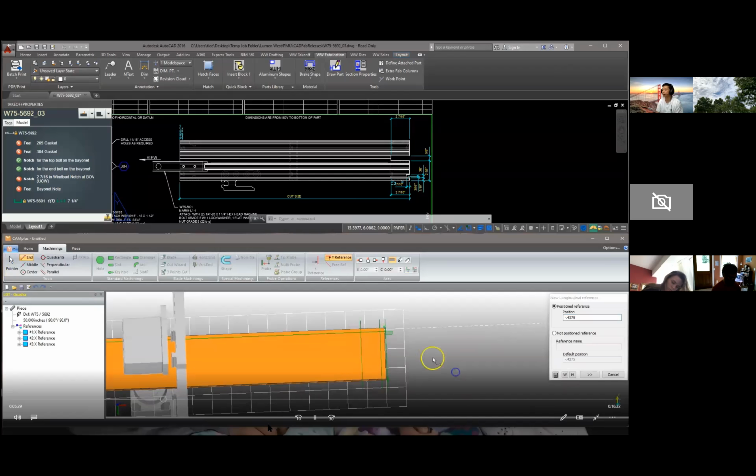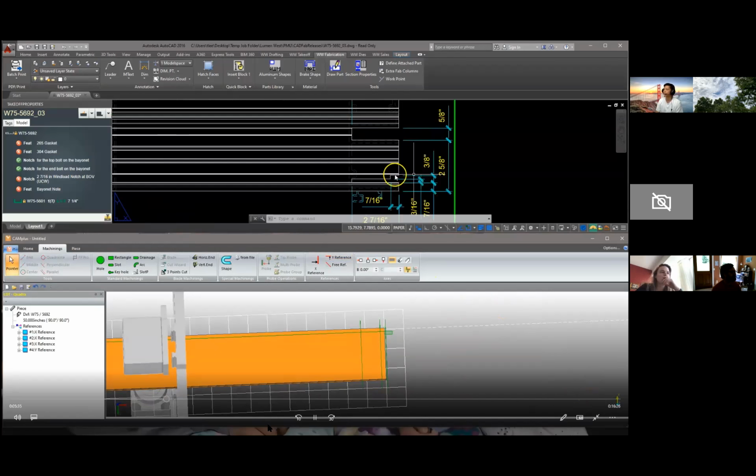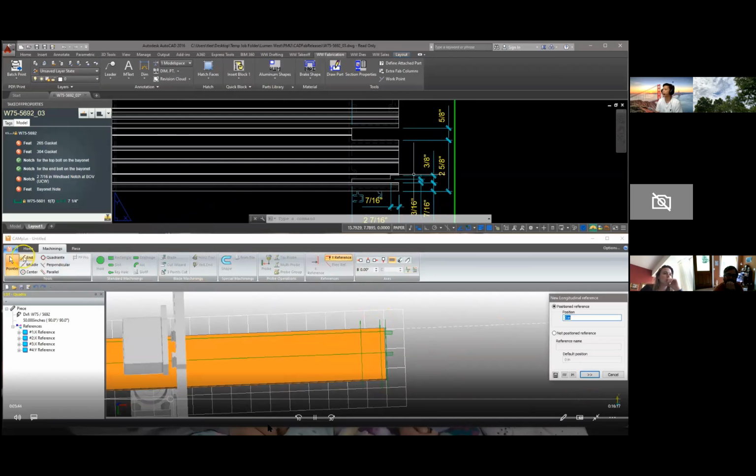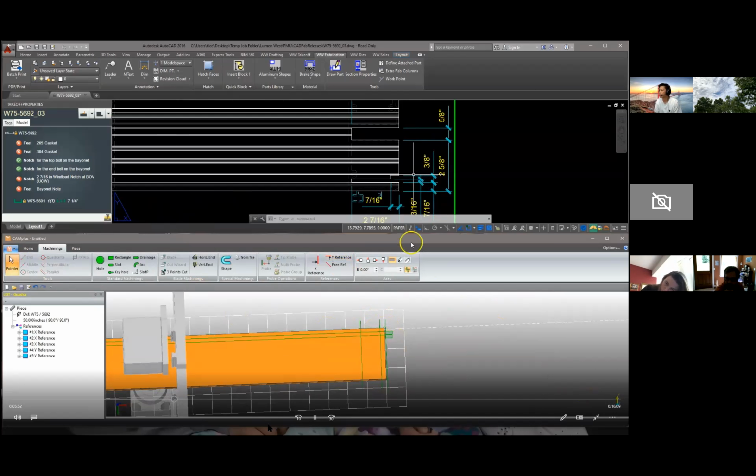So we pick the point at the back of the mullion and come back in to the notches. The first one is 7/16, and then the second one we chose to program is 7/16 plus 3/8, which is the guide between two notches. And I'll show you later why we're choosing that point.